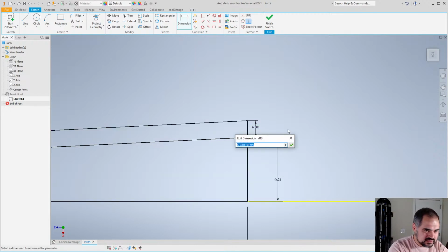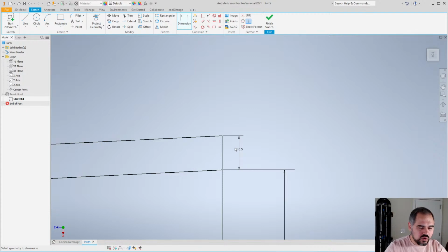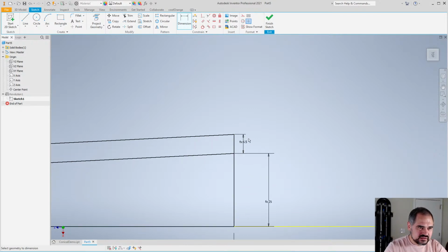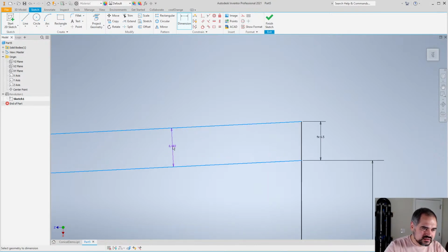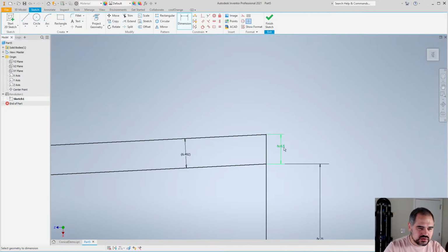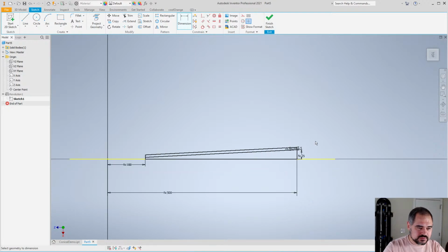I personally like to define my wall thickness by the wall thickness of the cross-section, which means anytime I take a cross-section of the instrument, the 2D cross-section will have a wall thickness of 6.5. It means that the perpendicular wall thickness is slightly less, 6.492. But if it's too small, I can always just increase the size of the wall thickness parameter. Okay.